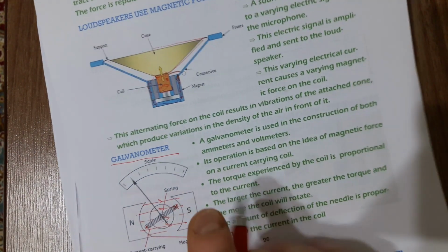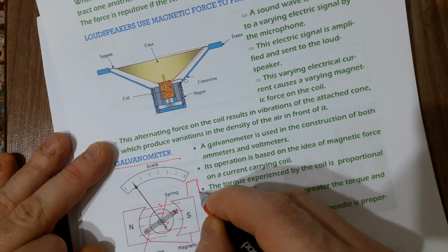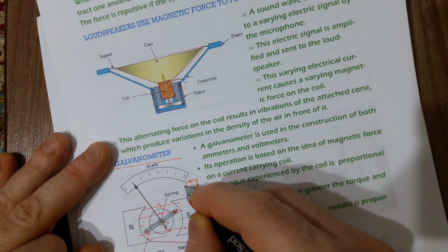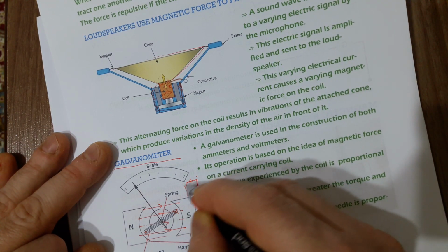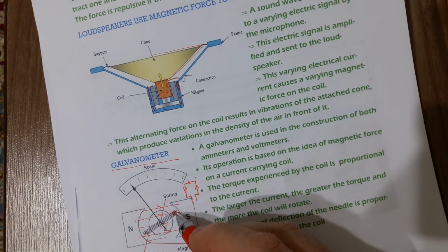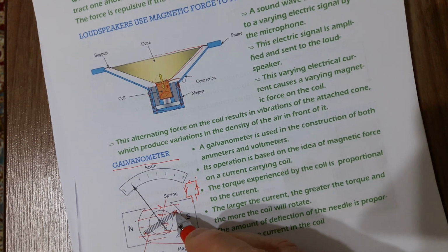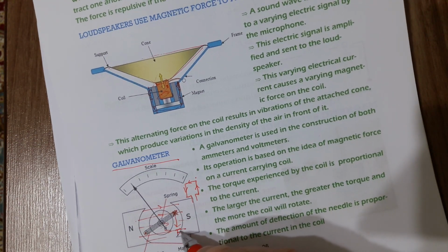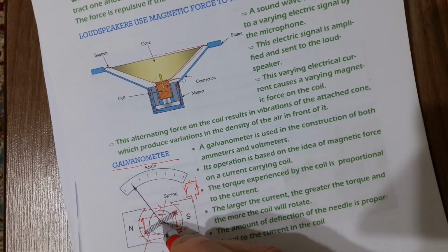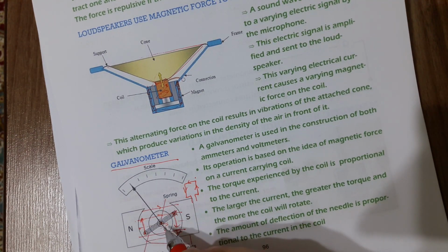From the rear view, if you look from above, you are going to see the coil like this. If the current is entering from one side, it is leaving from the other side. If it's into the page here, there it's out. So these currents are in opposite directions but inside the same magnetic field. For that reason, the forces acting on them are opposite. If here the force is down, here it is up. These forces produce a torque, a clockwise torque, which produces the rotation.